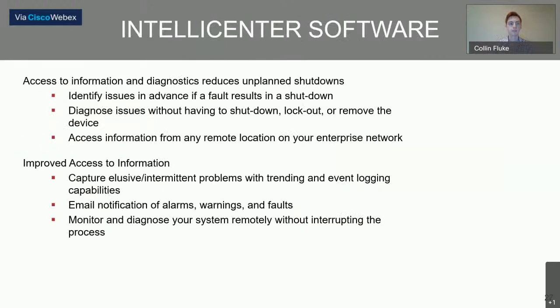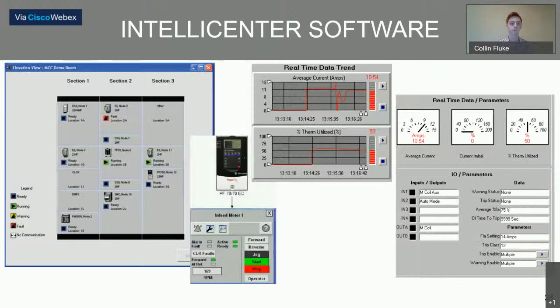So here we have an example of the software. The software that comes with the IntelliCenter MCCs allows you to run diagnostics, see real-time data of the entire MCC, as well as send notifications for alarms, warnings, faults, if there's a trip in the unit, anything like that. So let's take a look at some screenshots of the software.